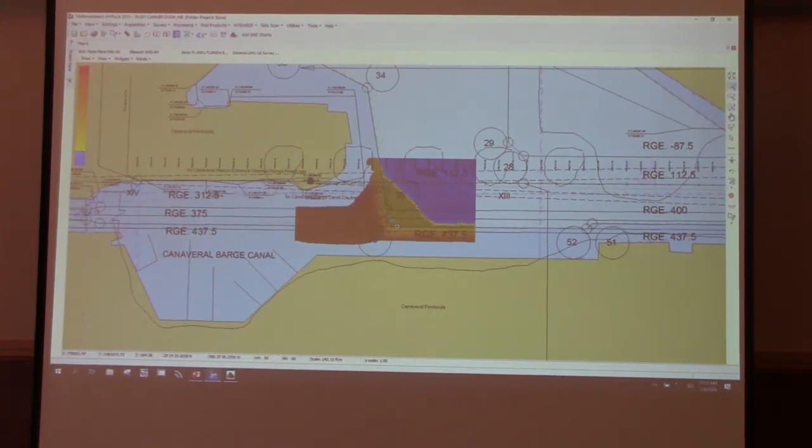Why would they want that as a GeoTIFF instead of an XYZ file? CPRD is requiring that in the job, for everybody that's doing multi-beam survey. GeoTIFF is an image file. It's a picture. Not in this case. We'll see. I think they're talking more about an ArcGIS grid. But it's a GeoTIFF. Maybe they have a way of embedding. Yes, you can build a surface and export a DEM as a GeoTIFF, and it's geo-referenced with Z values. Right. And then they can bring it in and run analysis or color it however they will.